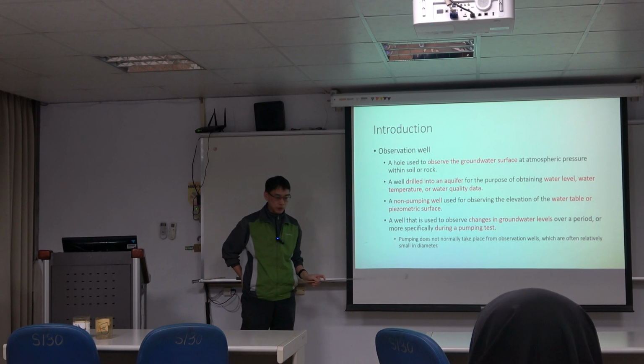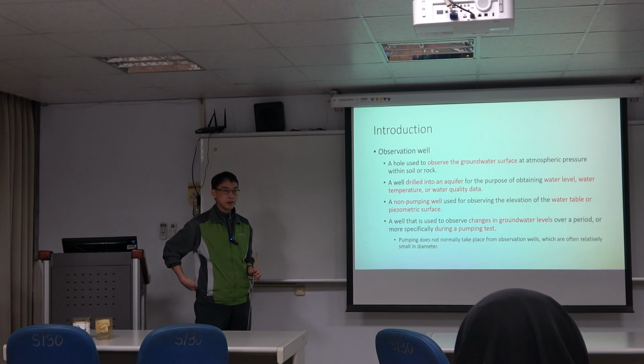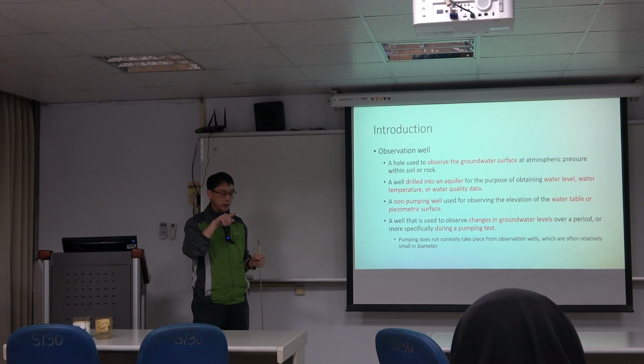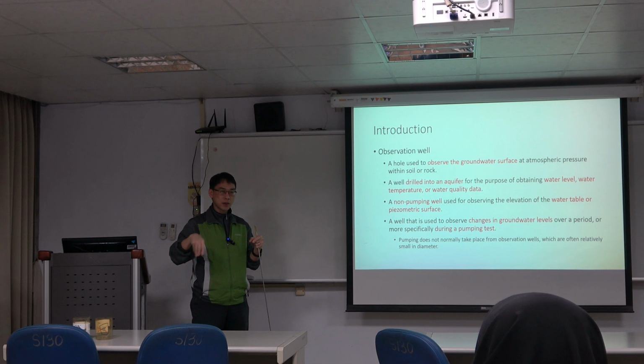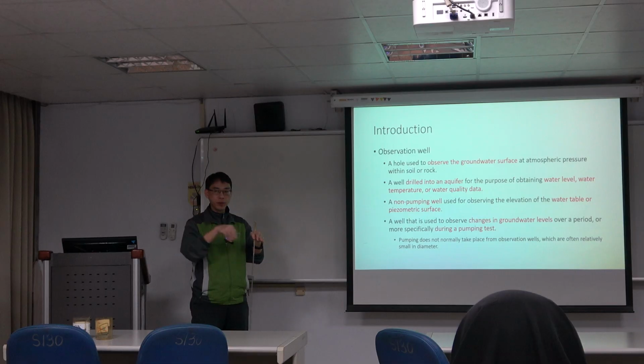And under some conditions, if we would like to use a multiple well test, like you assess the T values, in the following talk we are talking about the T and S values. To assess the T values, a single well is sufficient. But if you would like to assess the S value, you need to use a multiple well test, at least 2 wells, because you need the distance between the 2 wells, and then you will be able to invert the S values.